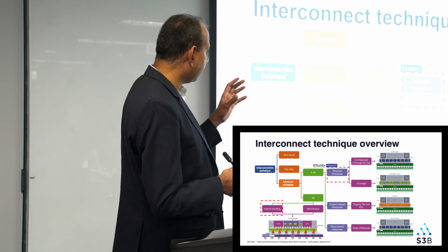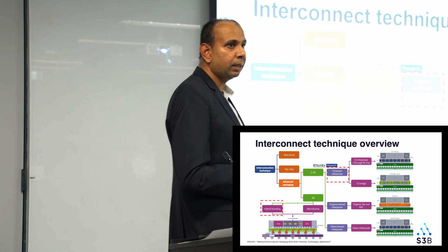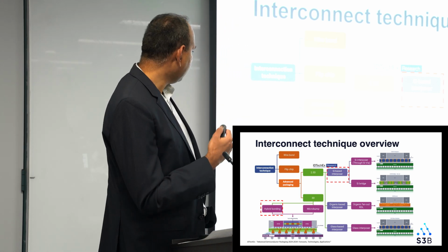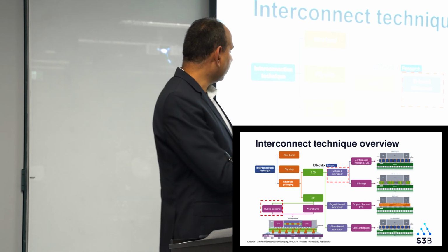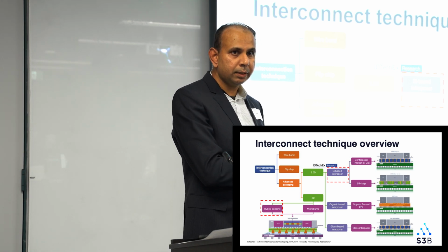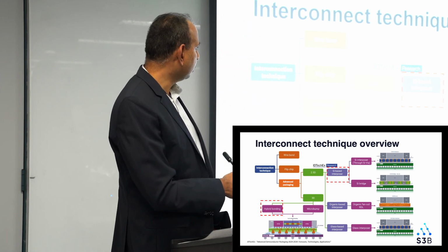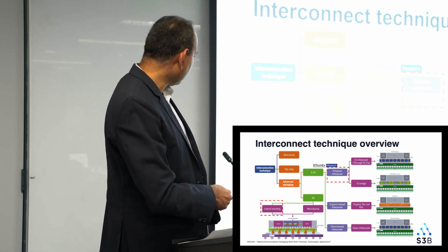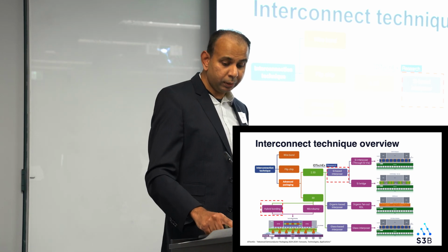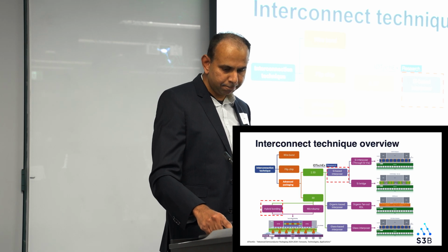So interposer technology predominantly dominates the 2.5D. And for the 3D, it's mainly hybrid bonding and the microbump process. In my talk, I've tried to focus mainly on the silicon-based interposer, where I will go through silicon via as well as the silicon bridge. And then I will also talk a bit on hybrid bonding before diving into the case studies.